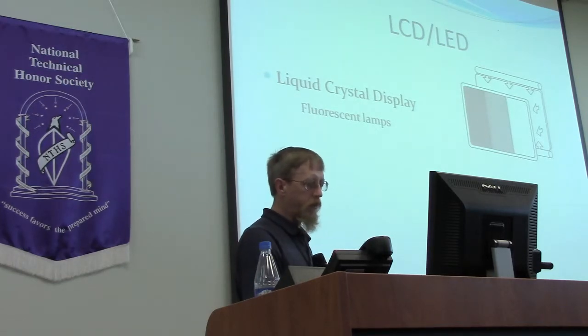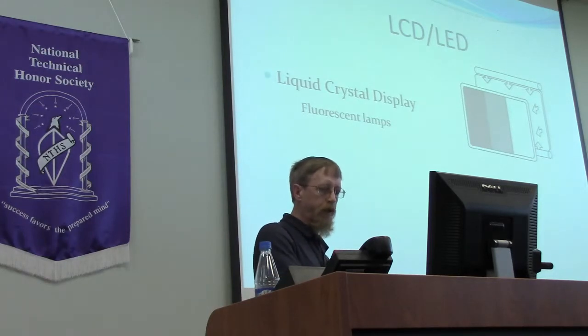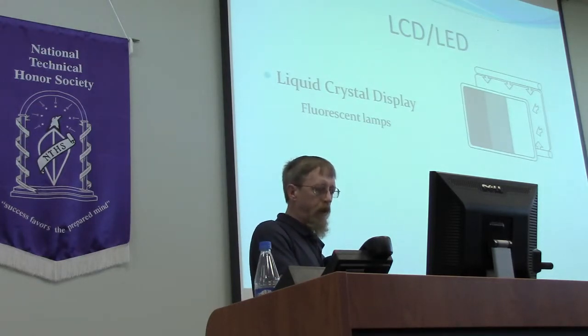The LCD panel is lit by two cold cathode fluorescent tubes placed on opposite sides of the display, and an array panel of CCFLs behind the larger display. A diffuser then spreads the light evenly across the whole display.